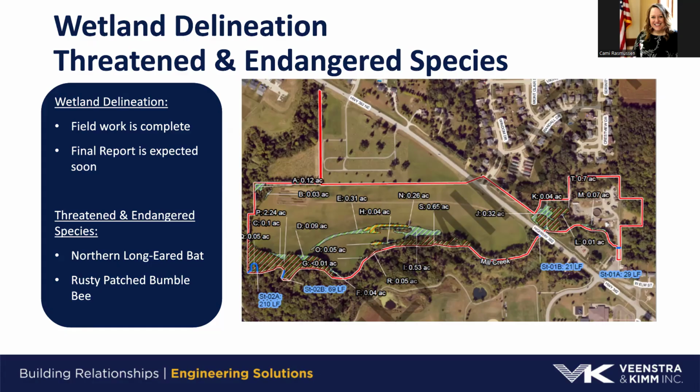The outfall down in the southwest corner is going to have a small area where the pipe has to extend out to that stream, that little oxbow. So we'll go through some of that forested wetland, but we'll keep that to a narrow swath. Then as we cross Highway 382 with the trunk sewer, we have to bore across that roadway, and there's going to be a large bore pit on the north side in that forested wetland area. We also have to construct a sewer over to the existing wastewater plant. Not all of that area gets disturbed that's shown there, but that just outlines the limits.